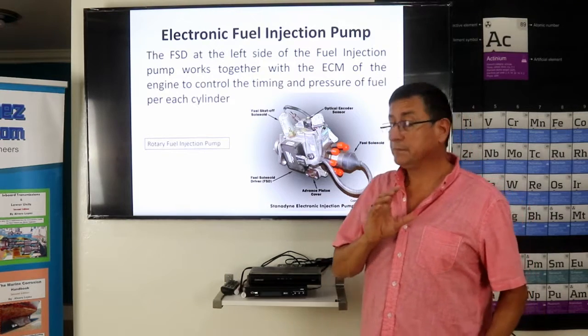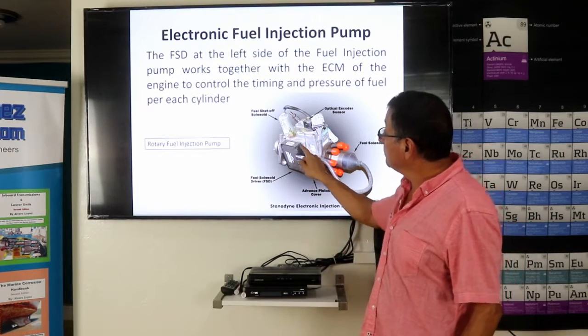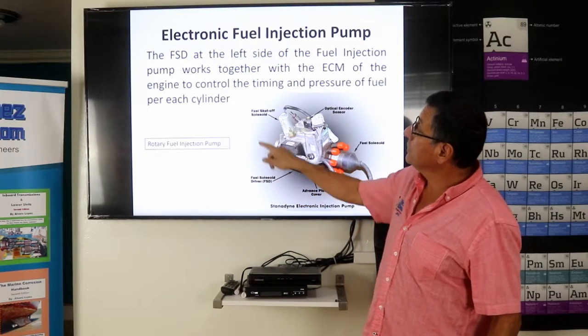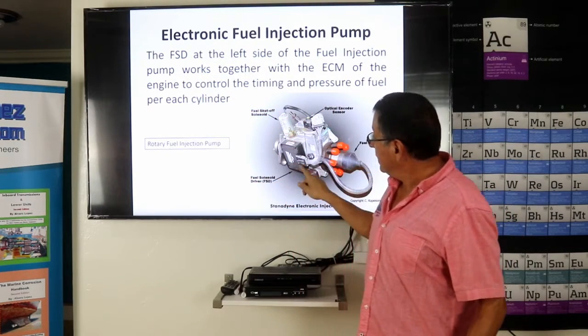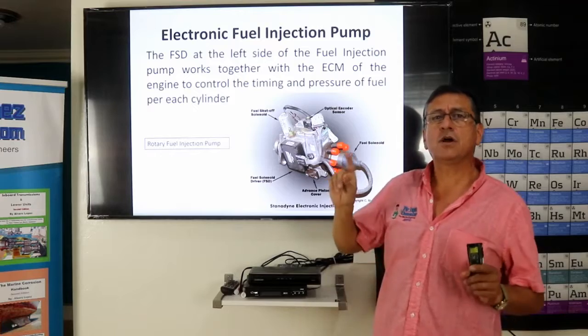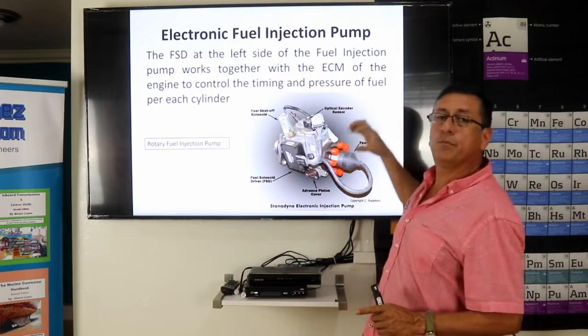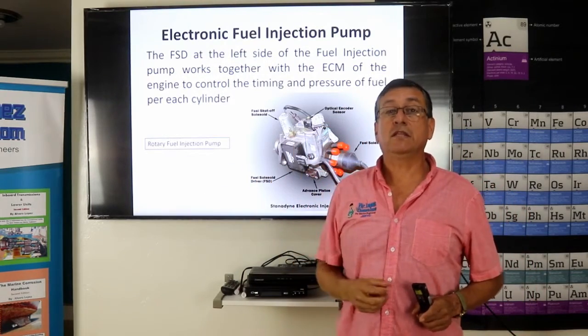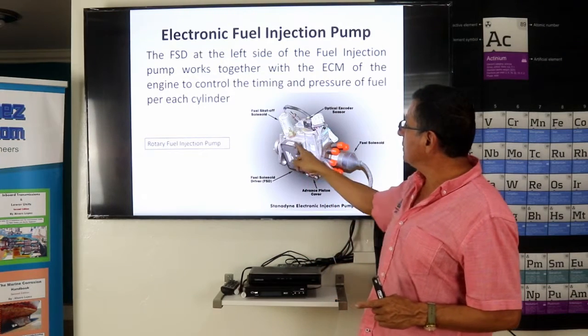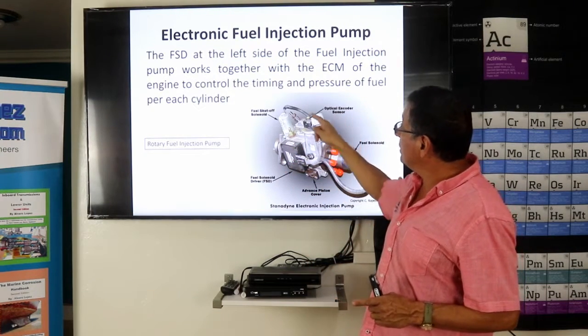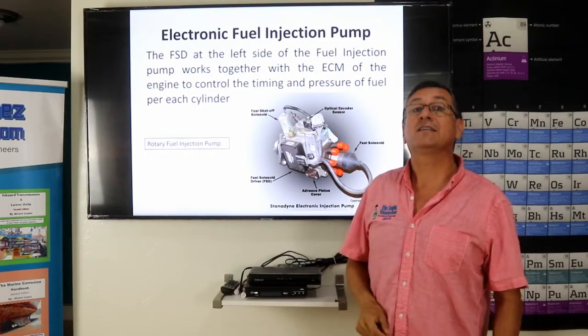The pump normally has a small computer. The name of that computer is FSD. That computer is talking all the time with the main computer of the engine, the ECM. The ECM sends the signal to that computer and also sends the signal to the stop solenoid.